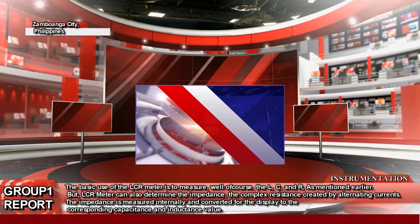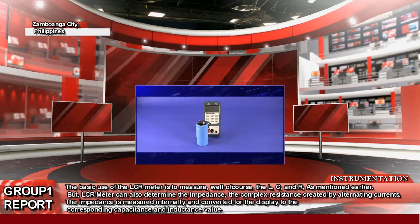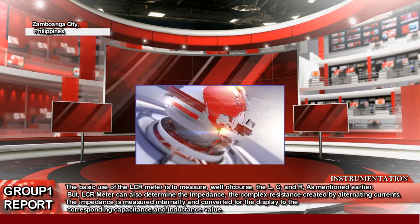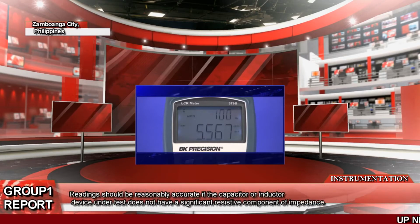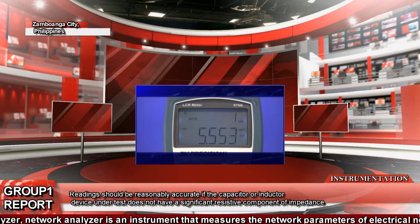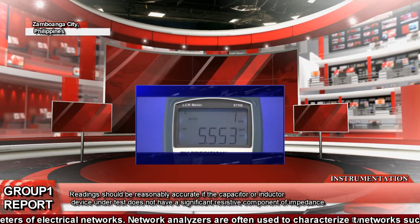The impedance is measured internally and converted for the display to the corresponding capacitance and inductance value. Readings should be reasonably accurate if the capacitor or inductor device under test does not have a significant resistive component of impedance. The LCR has two main techniques, namely the bridge method and the current voltage method.